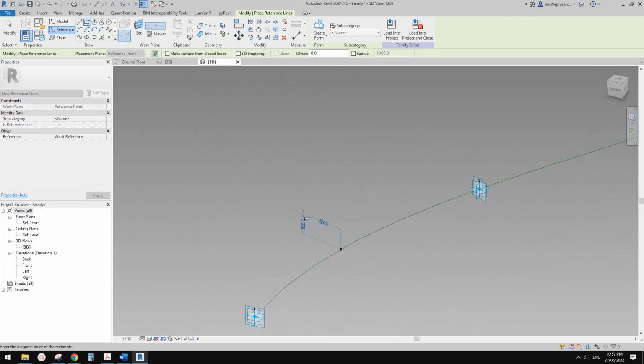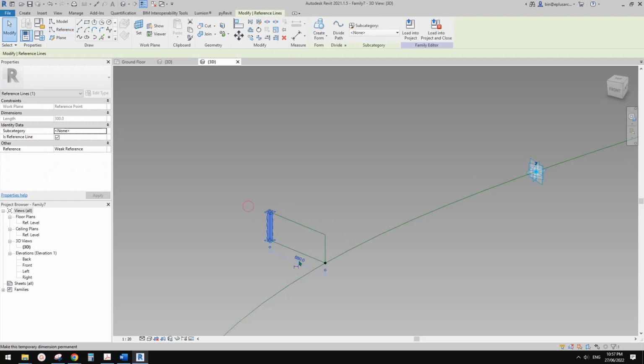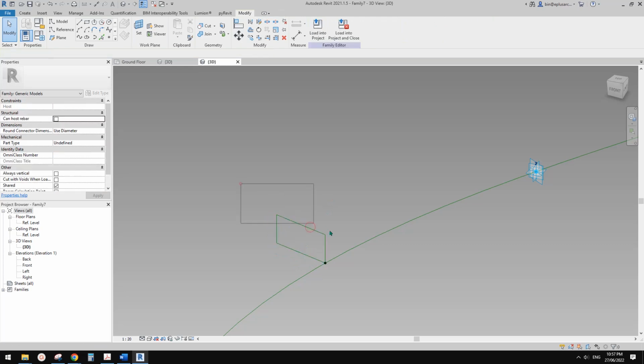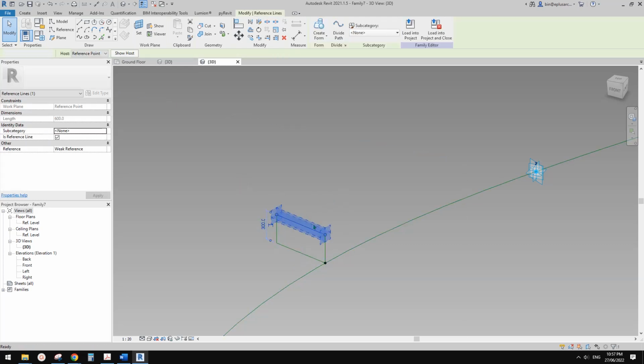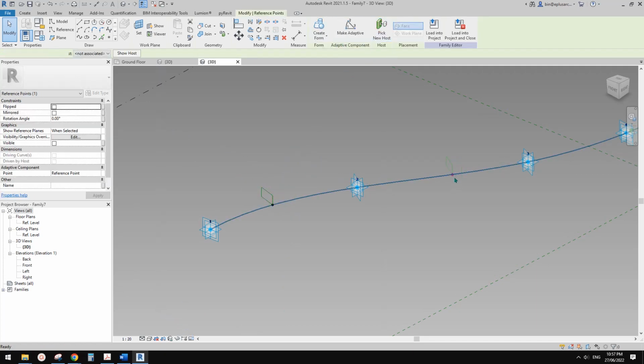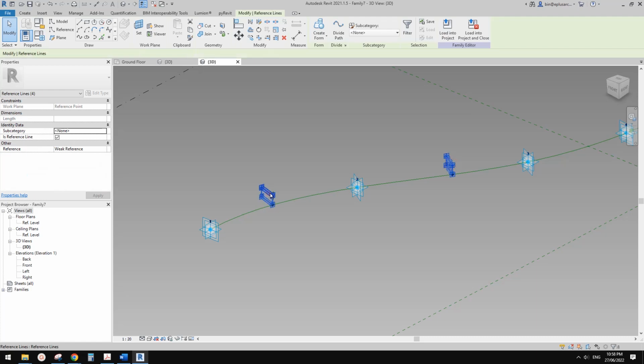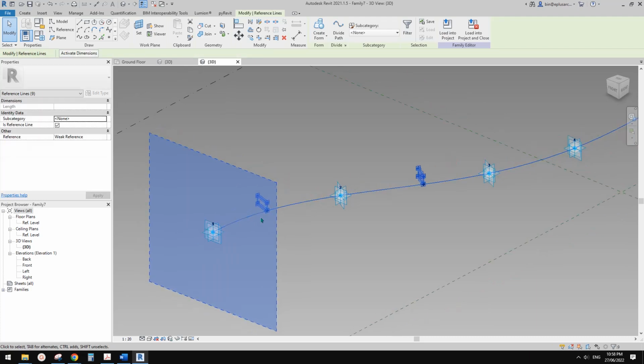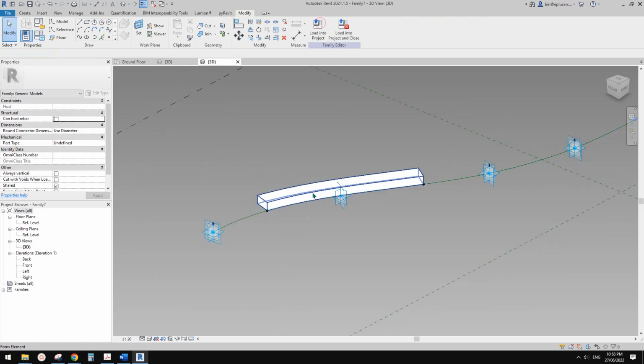So this shape needs to be 300 high, and for the depth, I'll just roughly let's make it 600. For the height, yeah, 300. That's all good. So copy this and pick new host and select these 2 profiles and get this path and create a form.